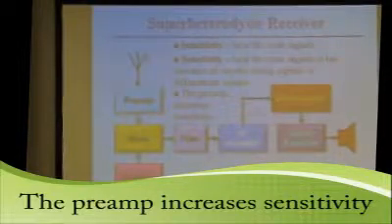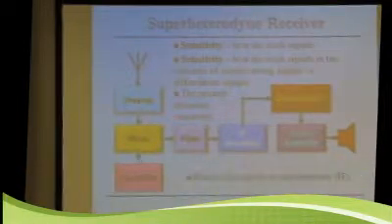And in this particular block diagram, you have a preamplifier which increases the sensitivity, so you can hear weaker signals. Then you've got a mixer with an oscillator, a filter. I mentioned the IF amplifier, intermediate frequency amplifier. Then it comes into a demodulator that takes the signal that you're hearing and actually demodulates the variable carrier through either single sideband or AM or FM or whatever, but for this particular purpose it was AM. Sends that to the audio amplifier and then out the speaker.